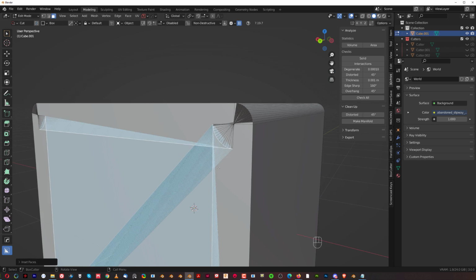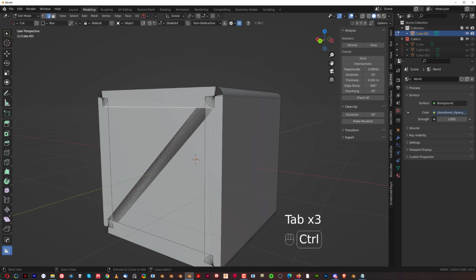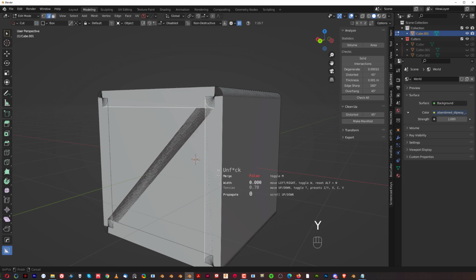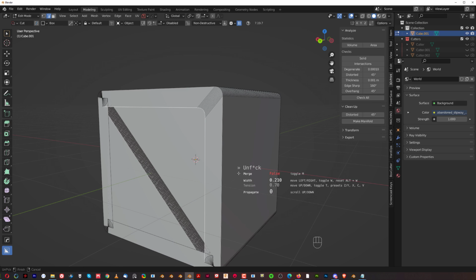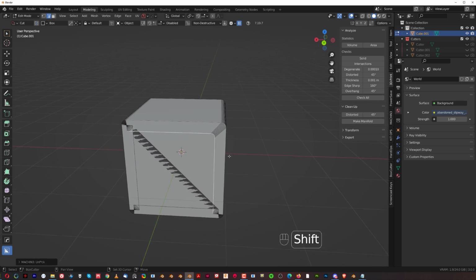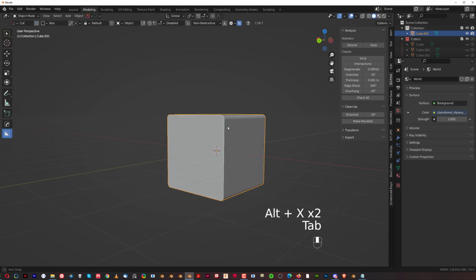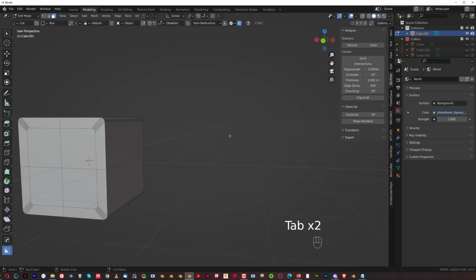With vanilla Blender, that's impossible. But with Unfuck, what I can do is select this edge and Control select this edge. So this edge here, which is an equivalent of this edge. Go to Y and Unfuck, and boom. And then all I do is use another tool that's actually fantastic in Mesh Machine, which is Mirror. Alt X, and I'm done. Okay, you know what I mean? That's how handy it is.